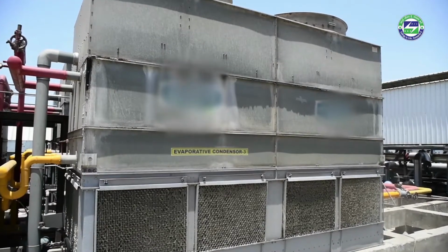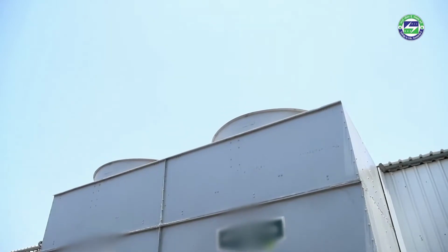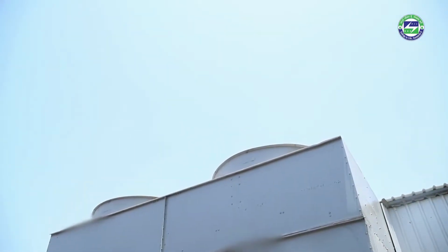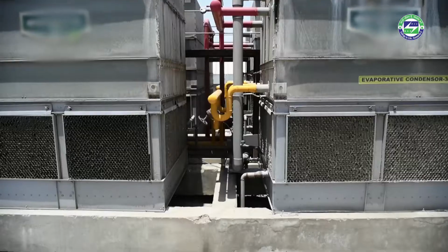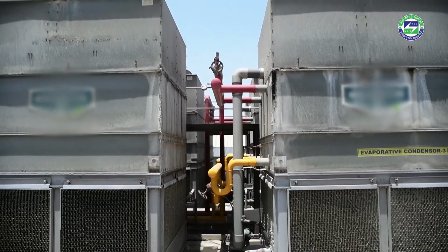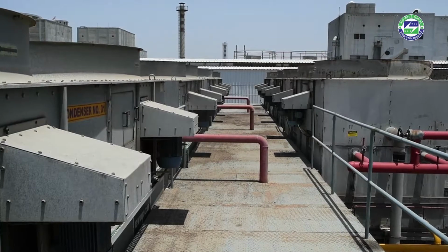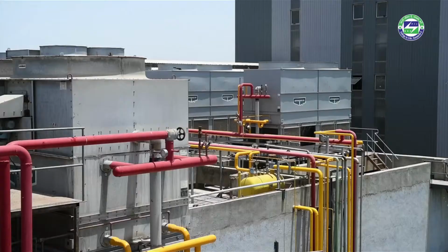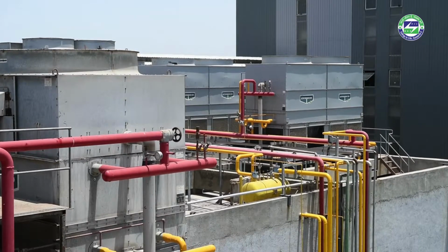An evaporative condenser is best suited for hot and dry regions. A condenser should be selected based on climatic conditions. One of the important parameters to ensure optimum efficiency in an evaporative condenser is to select the correct capacity of the equipment. Also, regular preventive maintenance allows maintaining optimum efficiency. Performance of evaporative condensers is affected in humid atmospheres.